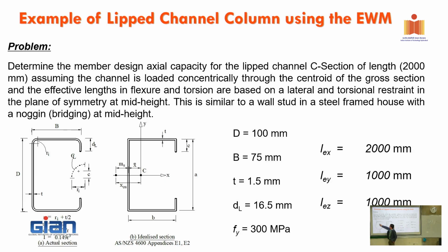In practice, you have to roll it, and then there's an internal radius in here. So normally R here is about 5 millimeter for the minimum requirement. If you make it very sharp, as we discussed with some professor here, then it might break at the corner, right? Because of very high concentrated stress, and it might crack. So you need to have a minimum requirement of the curve in here, what we call the internal radius.